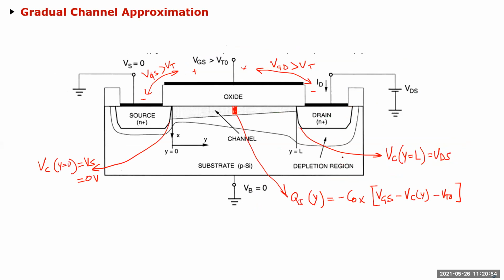Okay, now we are going to increase the VDS further. So now we can't make that approximation that the sheet charge is constant. Now we increase the VDS. Now you can imagine, because I have the source and the drain, right? And this is ground, and this is some voltage VDS with respect to your bulk. Now you can imagine. So if I slice these, right?